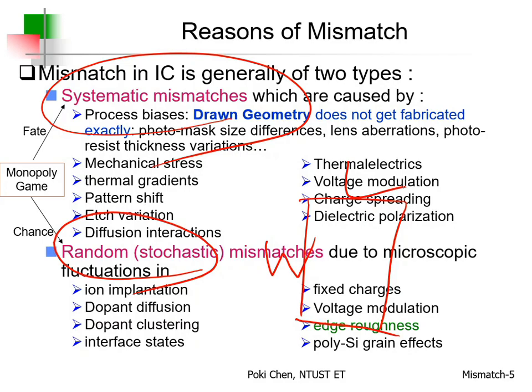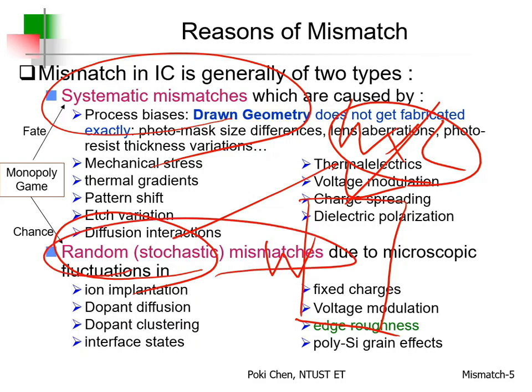The larger device area, I'm talking about W by L instead of W over L. Okay? 是面积哦，不是除哦，是乘法。The larger device area, the smaller random mismatch. That's it. Okay? Don't tell me, I have some kind of random mismatch. How to deal with it? Oh, very simple. Just increase the device size. Oh, no, the device area. That's it. Okay? No more. That's it. Only one way. Only one solution. But how about systematic mismatches? We have a lot of the so-called layout patterns for help. All right?